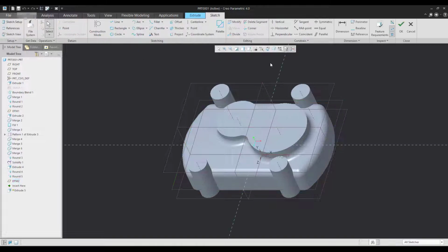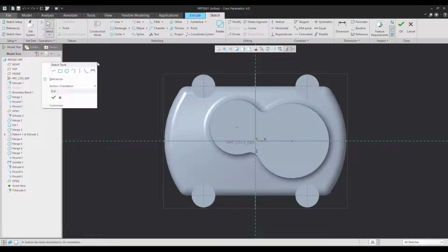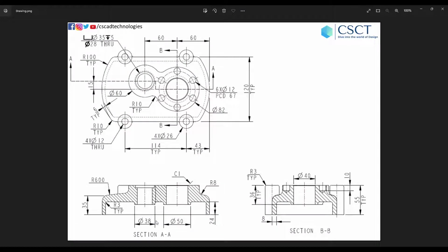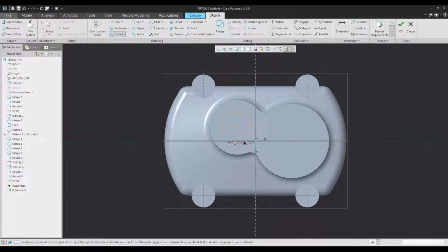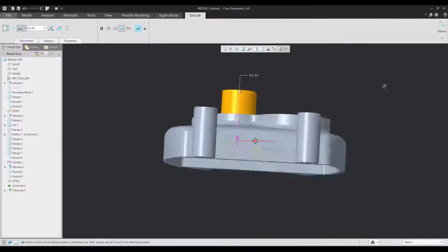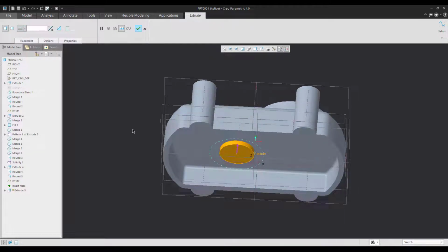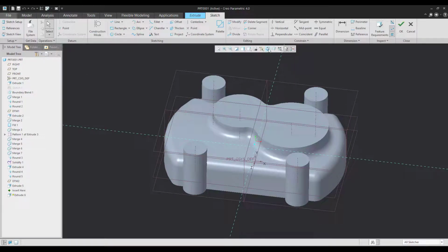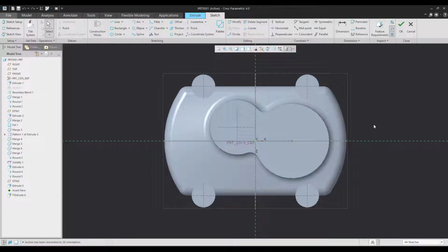On this, I'll make an extrusion. Now the first one is actually in line with this circle. So I'll take that as the reference and add the 38. Till the next surface. Now, the same one is on the 36 plane, but with this as the center reference.